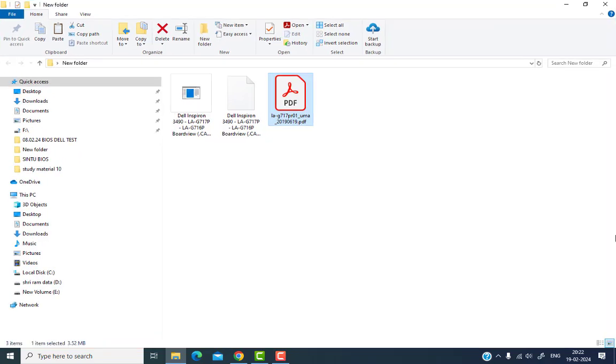Hello friends, once again. In this video, we are going to learn this deeper section, this schematic diagram, like the pin out on the SIO. If the laptop is not powering on, then which pins do we have to check on the SIO? And for that, we are going to use a schematic diagram as well as a board viewer. So here is a diagram.